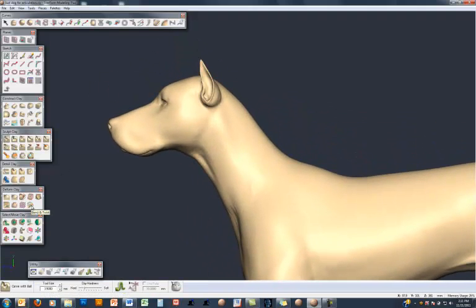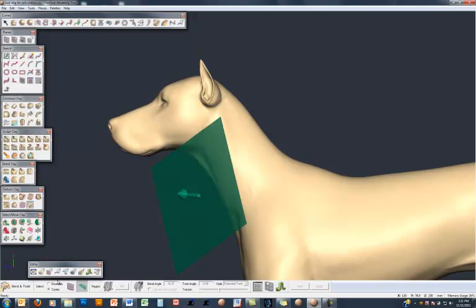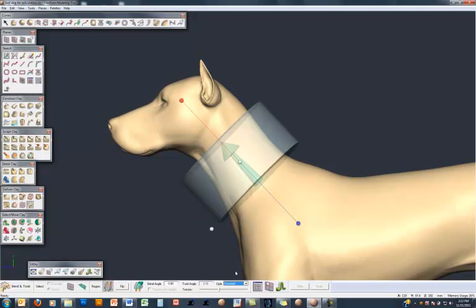So I go to the new bend and twist in the deform clay palette. And first off, you see we have this slice tool on the end of my stylus on the Phantom, and wherever I click, this is where my bend zone, my bend widget is going to be placed. Now the angle of the widget is completely dependent on the angle of the plane that I freely put in there. At this stage what we can do is manipulate the widget around.